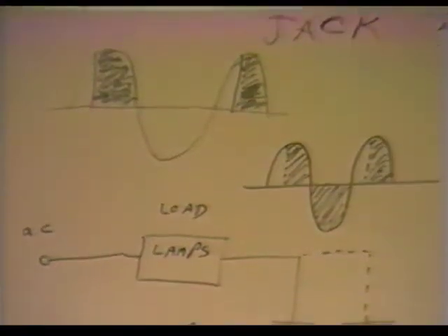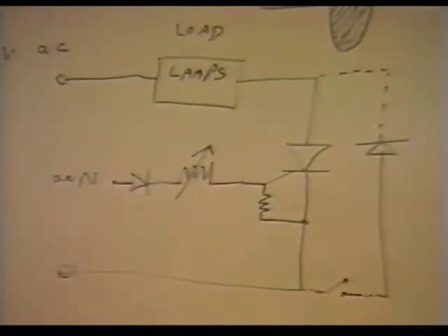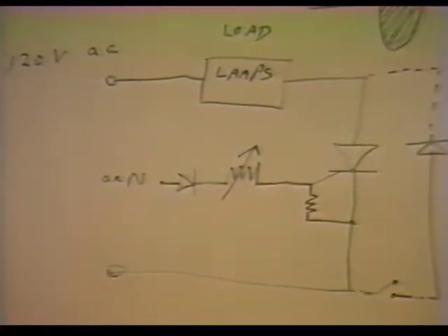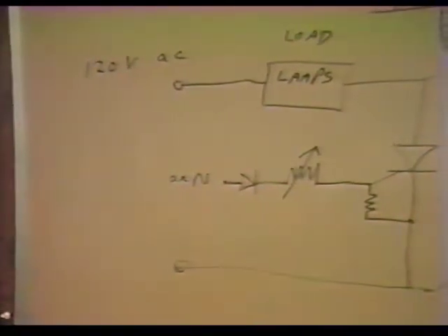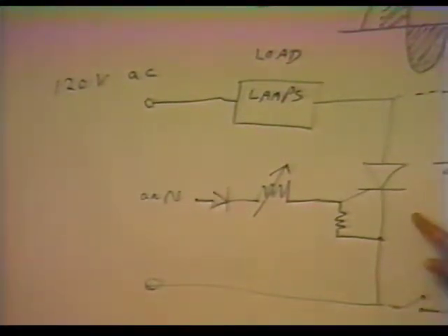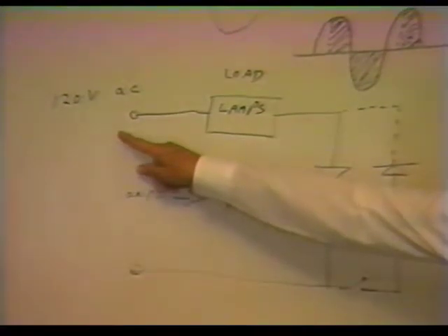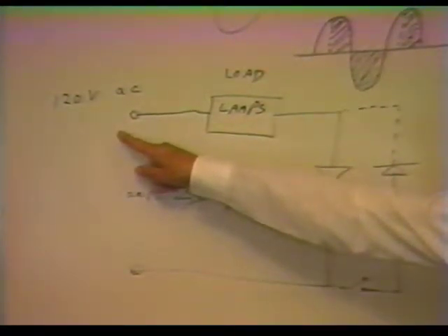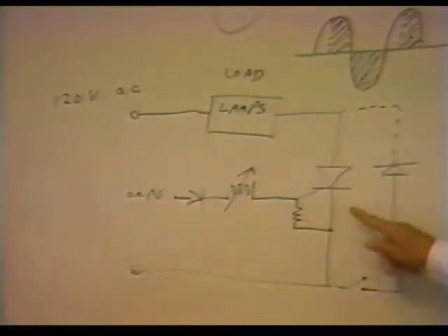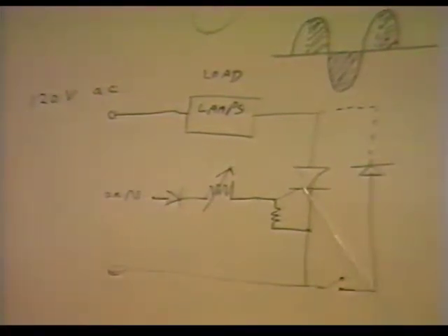So if, for example, we turn on a light, you've got 120 volts, and you get the full brilliance of the light. Now, if you want to dim it, you have to reduce the overall current going through the light. The way that's done with an SCR is quite simple. We have an AC signal coming right off the power line going in to light your lights. The lamps over your table are the load. The SCR is connected across the AC power line, and we have the gate. The gate controls the SCR, turning it on. It does not turn it off, it turns it on.